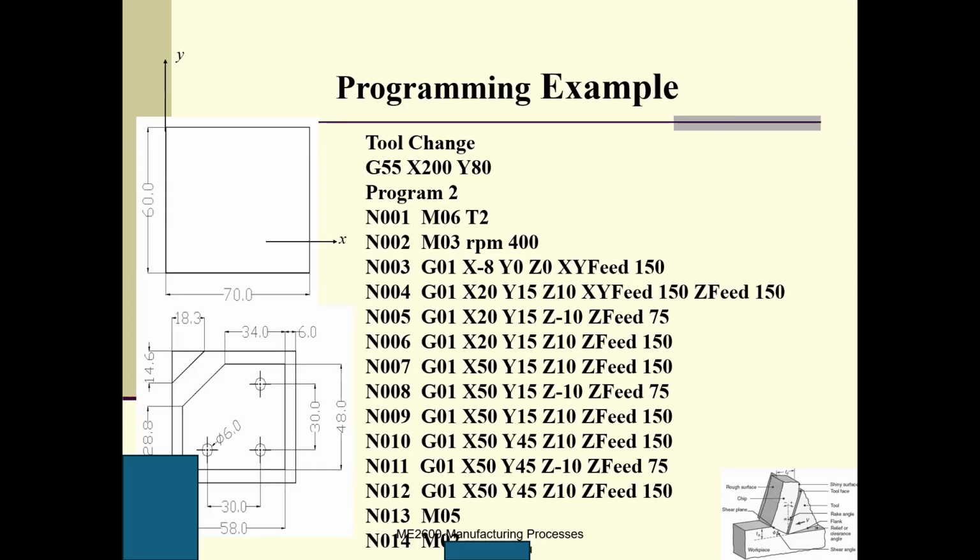Okay, this is my drill a hole. After I drill the hole, I move back. G01, x20, y does not change, z. Now after I drill the hole, I come back. My tool is elevated. I come back. But the XY position does not change. You would really write line 6 as just Z10, because the rest of your code is the same. So this is my original position.